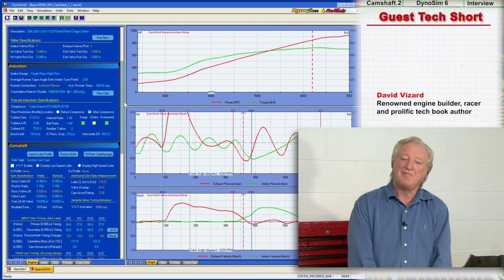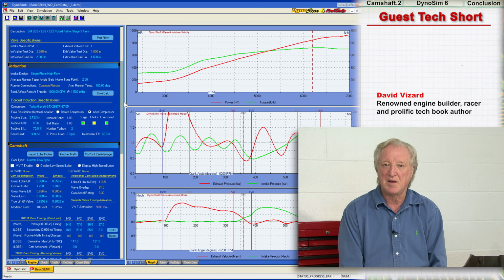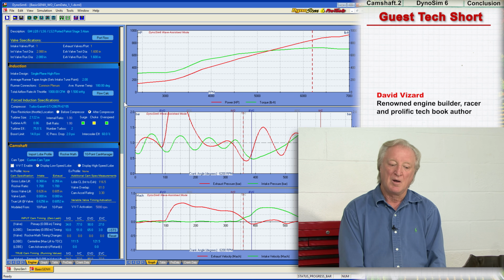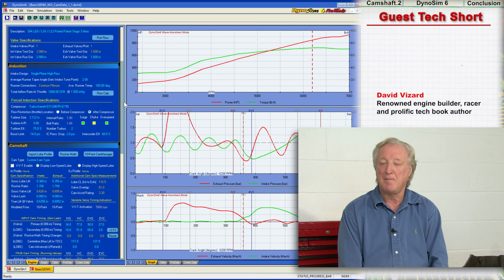If you then have the resonator box dumping into a muffler that flows at least 2.2 CFM for every horsepower the engine can make on an open exhaust, the engine will not know the mufflers are there. So, by having the expansion box or the resonator chamber and a muffler with 2.2 CFM per horsepower or more, we have got a system which is invisible to the engine. Result, 0 change in power.